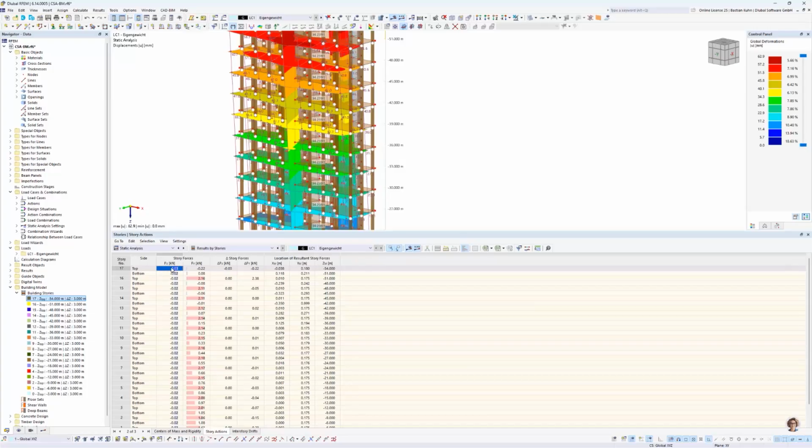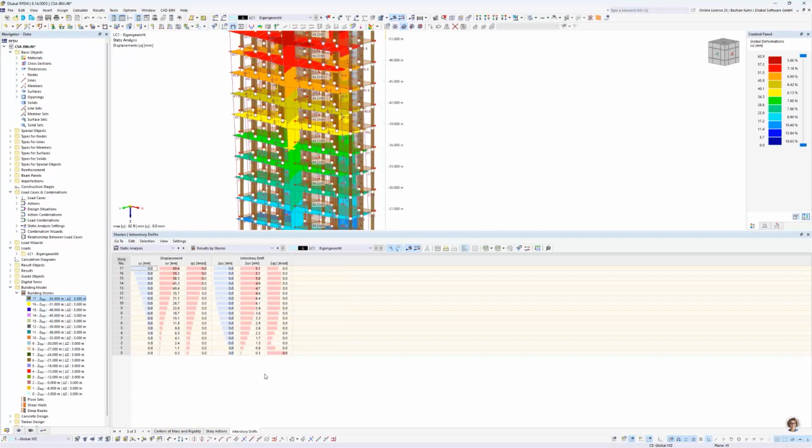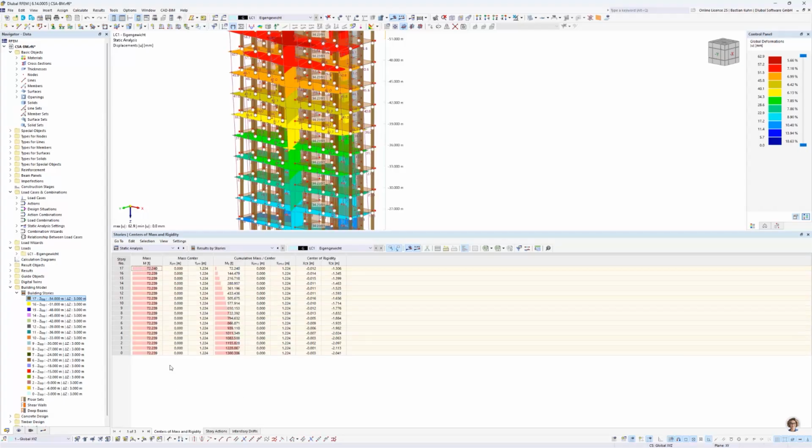So all the stiffening elements, okay, we do not have wind load or earthquake load in here, but imagine we have defined it or arranged it. It would give us the information: this horizontal force is transported in X direction. How much mass do I have to activate in here? And we have the deformation of each story.